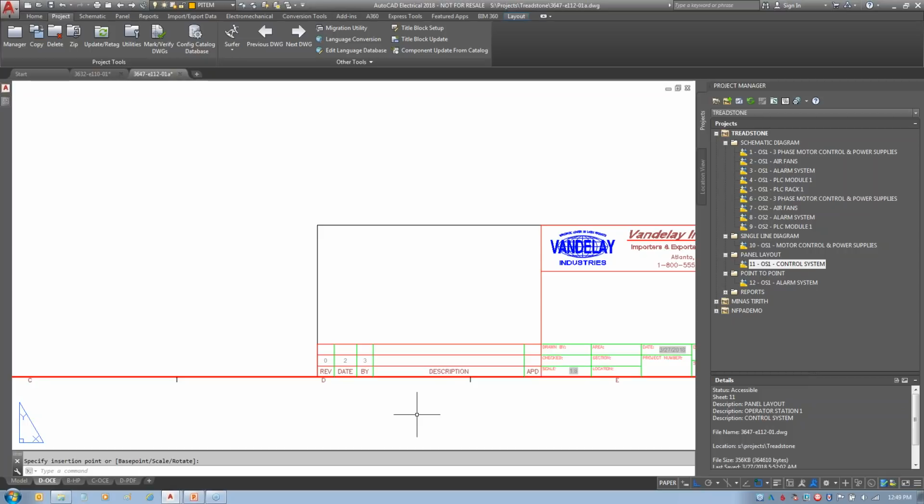Vault would kind of resolve that issue for you. So I would recommend Vault as the ultimate method, but if you don't have Vault, this would be an alternative. So if you wanted to create the WDL and the WDT files manually, meaning not using any tools within the software, you could in theory just create a text file, name the extension WDL or WDT, and place it in the root of the project folder, correct?